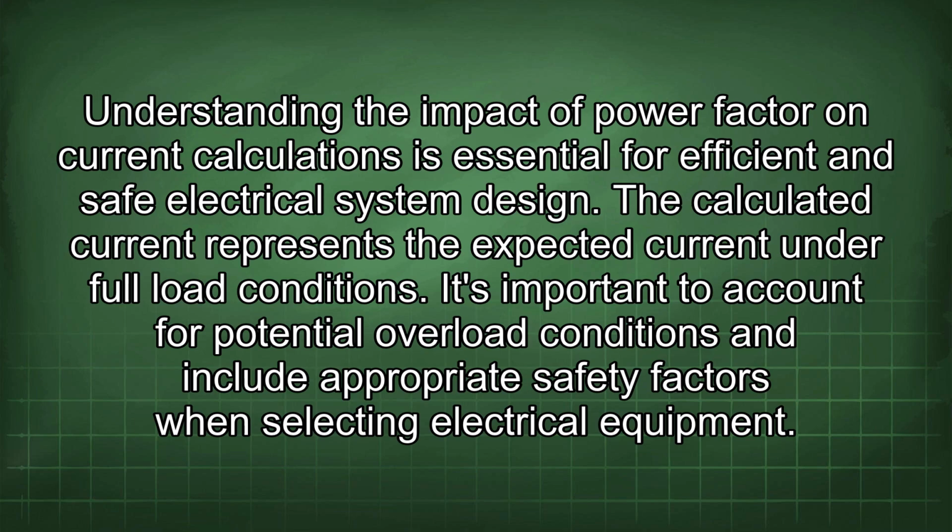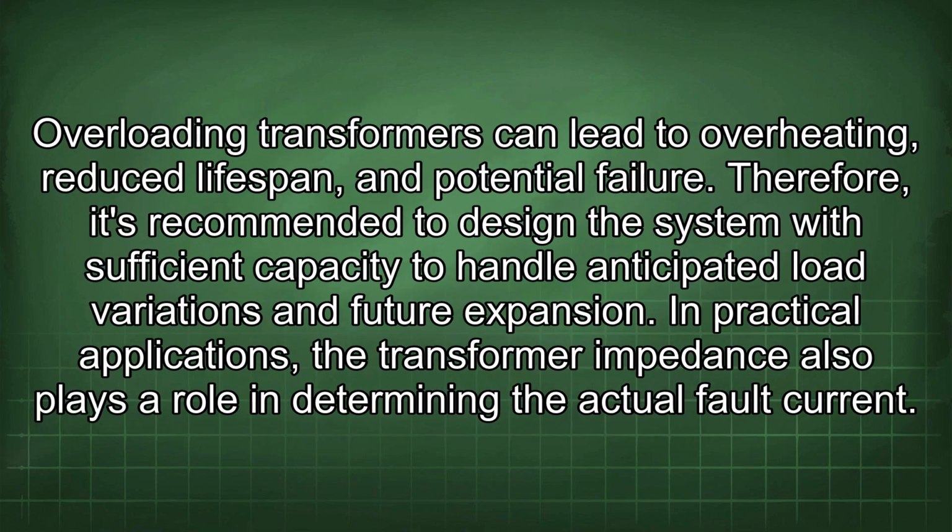The calculated current represents the expected current under full load conditions. It's important to account for potential overload conditions and include appropriate safety factors when selecting electrical equipment. Overloading transformers can lead to overheating, reduced lifespan, and potential failure. Therefore, it's recommended to design the system with sufficient capacity to handle anticipated load variations and future expansion.